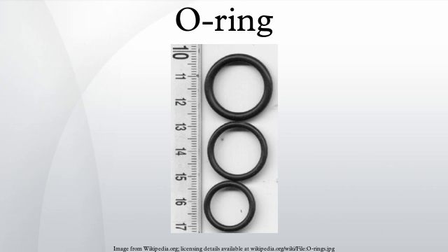The seal is designed to have a point contact between the O-ring and sealing faces. This allows a high local stress, able to contain high pressure, without exceeding the yield stress of the O-ring body. The flexible nature of O-ring materials accommodates imperfections in the mounting parts. But it is still important to maintain good surface finish of those mating parts, especially at low temperatures where the seal rubber reaches its glass transition temperature and becomes increasingly crystalline.